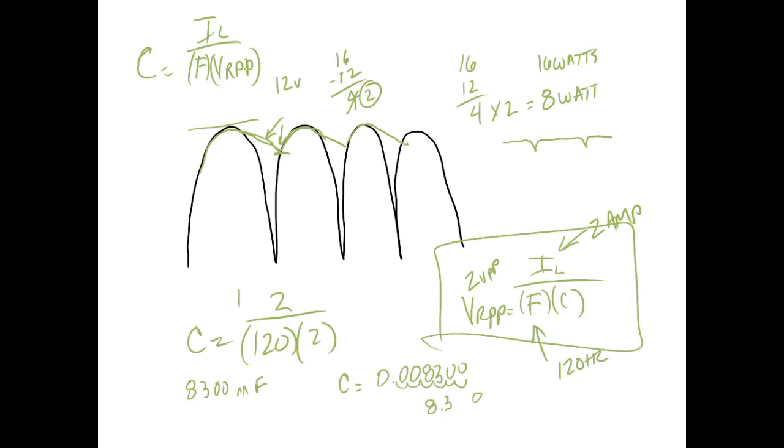So that makes sense. But the bigger the capacitor you choose, the more expensive it's going to be. Consider the problem we have with big power amps in a car: where do they usually mount the power amp? In the trunk. So your stereo and your speakers are up here in your cab, and your power amp is back in your trunk, and you have a 1,000-watt amp. 1,000 watts at 12 volts is a lot of current, right?